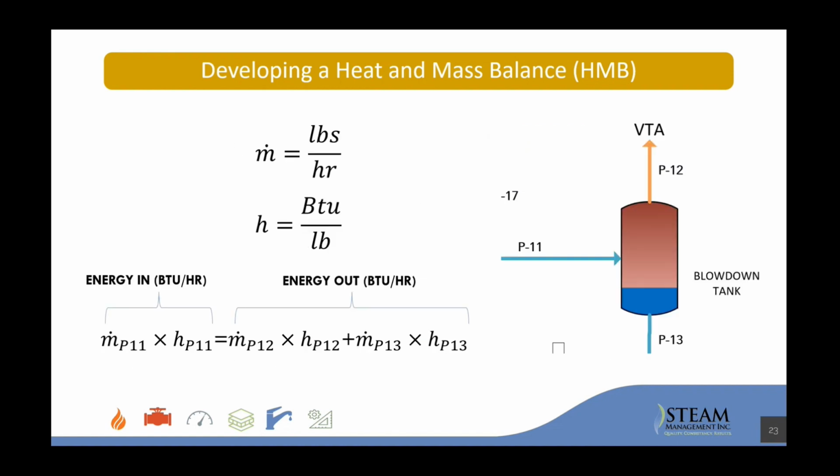Hey, Chase, if you don't mind me interrupting, we have a question from Clade. The question is for pressure reduction. Is there a typical rule of thumb for distribution losses? For example, if there is a hospital making 100 psig steam and the highest user is steam sterilizers at 60 psig, is there a way to estimate what the psig should be at the plant for the normal conditions? No blowdown through traps, leaks, etc.